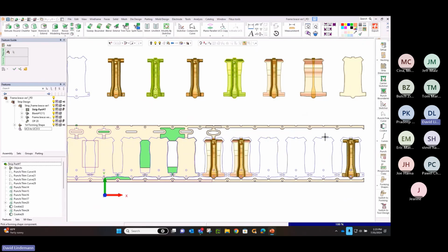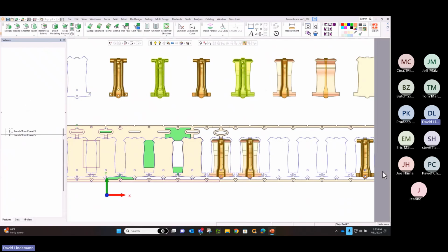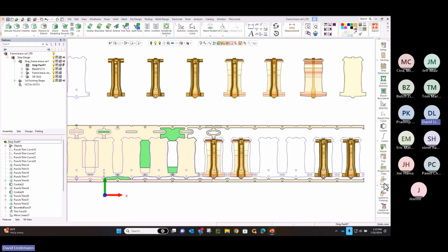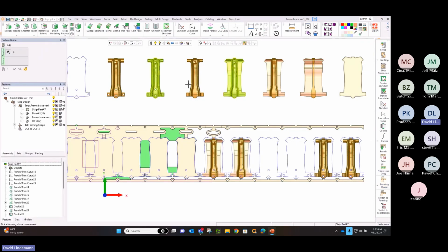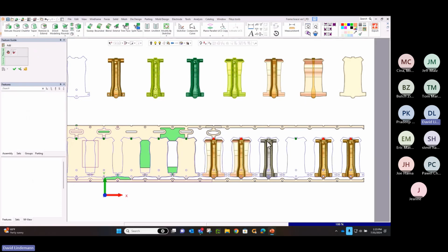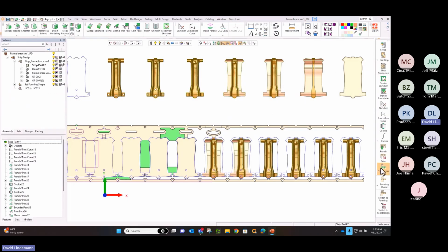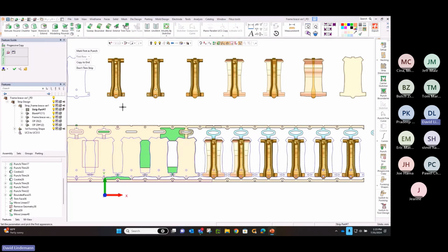And then I can say, before we do that, let's also add that same shape again. And I'm going to be concerned about those punch holes that are remaining. The decision might be instead of punching them up at the front, I'm going to punch them here at the end because of how much that shape changes. That way I get the correct shape of the hole. And I'm stretching it. So I position those.